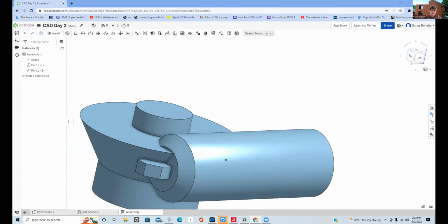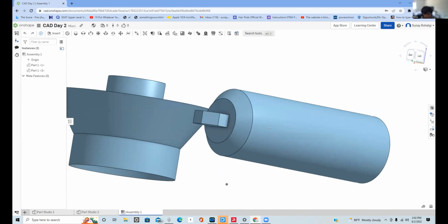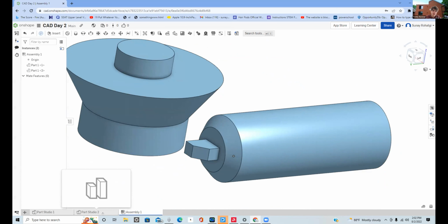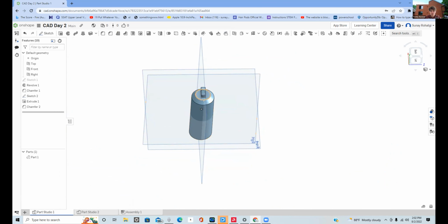The reason it's like that is because you didn't define it right. So you just select to see the radius of where you want the cap to be. You need to select the edge of that circle. Perfect. So the diameter is 20 millimeters, so if you want the cap to go on that part, it has to be 10. Exactly.